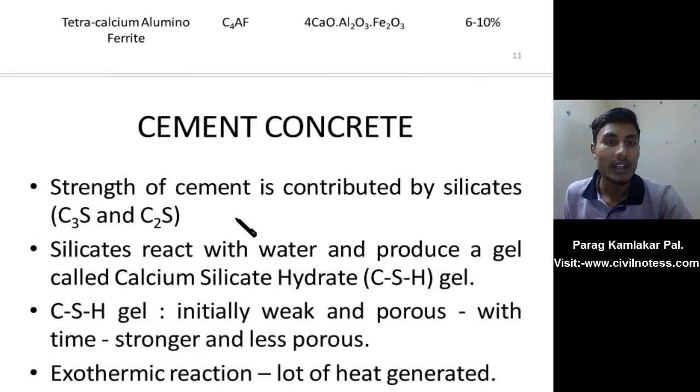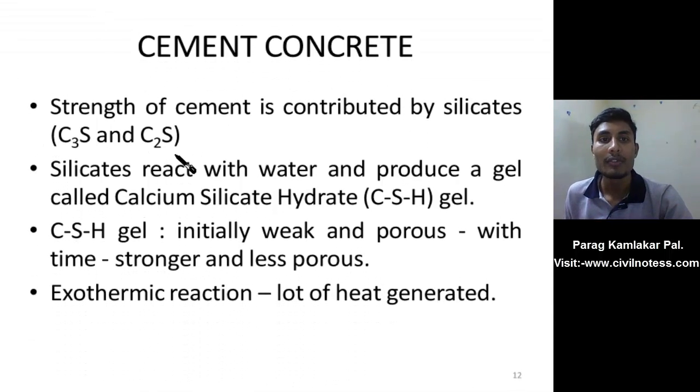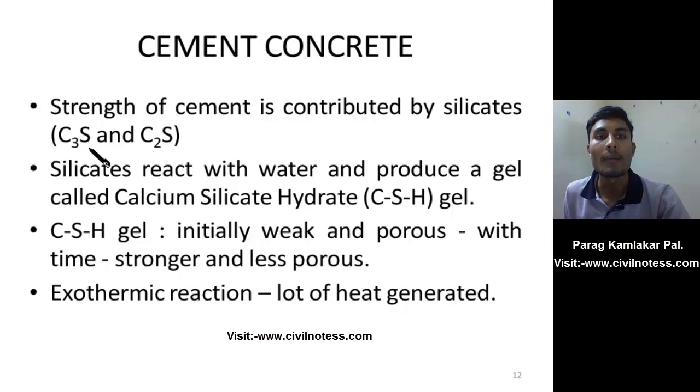Okay, after that, one of the main differences is between tricalcium silicate and dicalcium silicate. Tricalcium silicate helps to impart the early strength, up to 7 days. It contributes to gaining the early strength in 7 days. The remaining strength is gained by C2S.